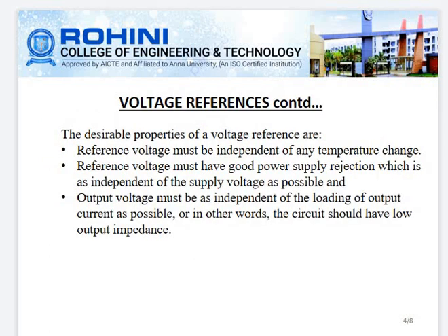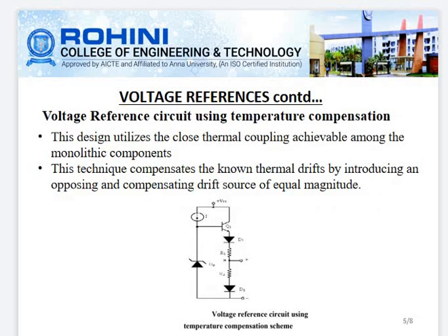The desirable properties of a voltage reference are: the reference voltage must be independent of any temperature change. It must have good power supply rejection, being as independent of supply voltage as possible, and the output voltage must be as independent of loading output current as possible, or in other words, the circuit should have a low output impedance.